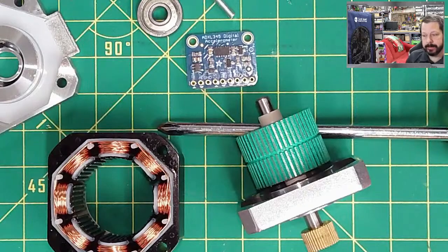Record that, and it basically goes in and uses a variety of models to measure the natural frequency at different printing speeds of your print bed. I guess the natural frequency doesn't change, but it measures the resonance at these different printing speeds and predicts what it needs to do, so that if it's trying to print a straight line but the bed is shaking back and forth because it's just moved, what does it need to do to compensate for that shaking?